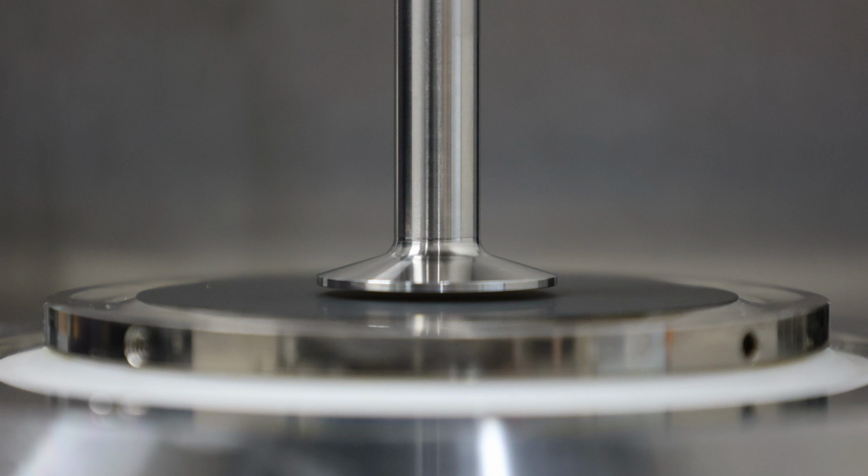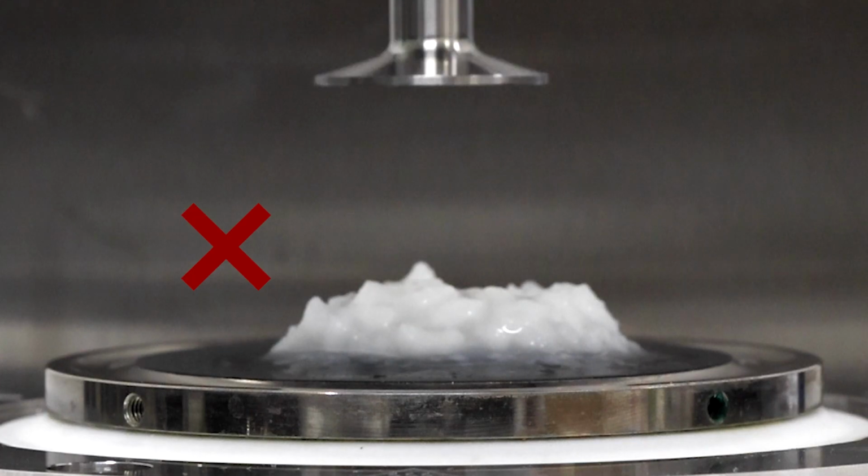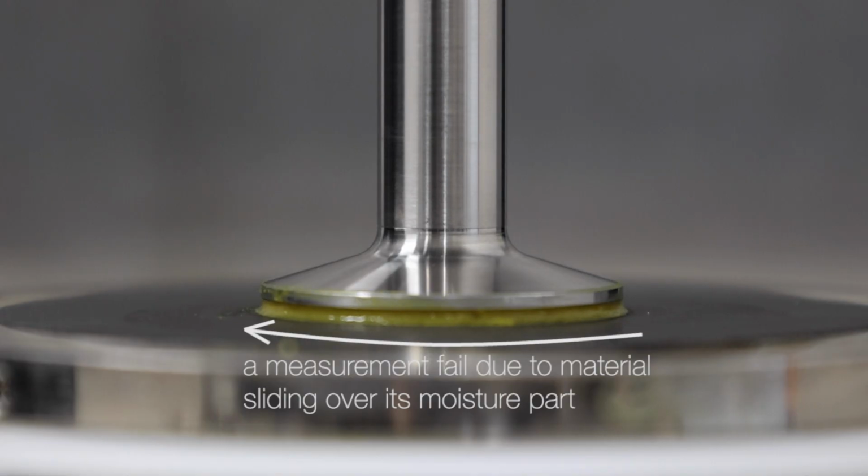For an accurate measurement of the flow curve, they typically encapsulate the specimen in an extremely thin gap, which excludes materials with large-scale inclusions. Even for materials without large-scale inclusions, the measurement can be unreliable if the moisture separates from the material and the material slips over the moisture, like this mustard example.